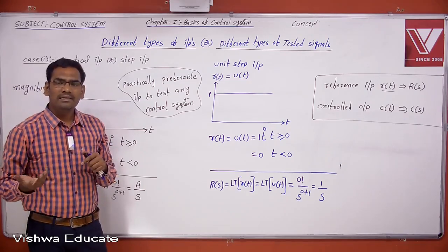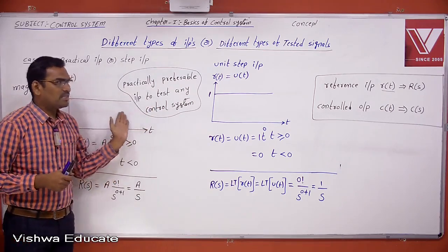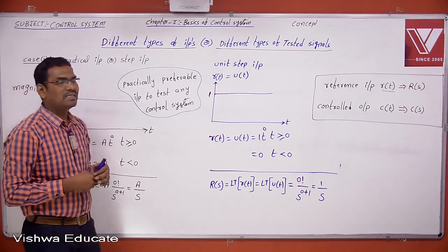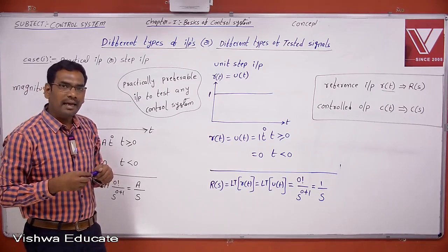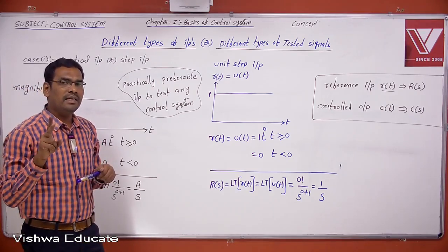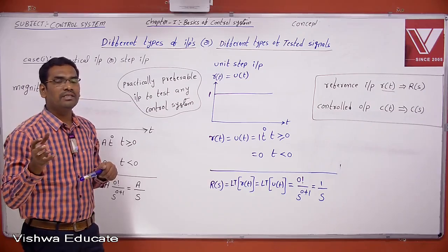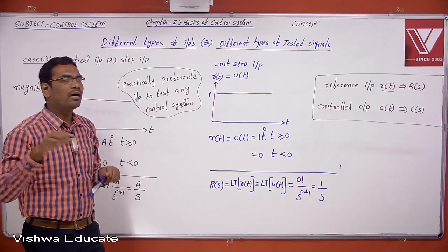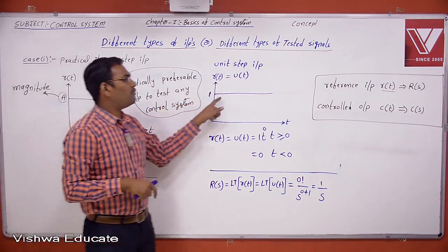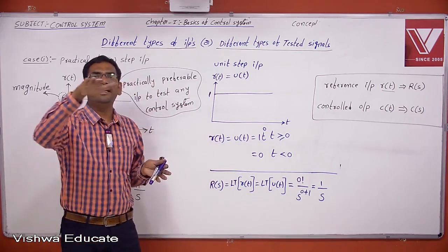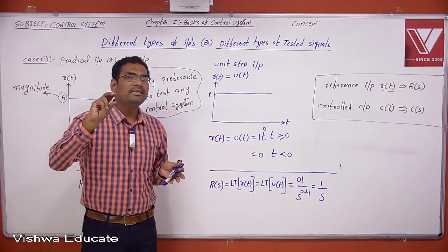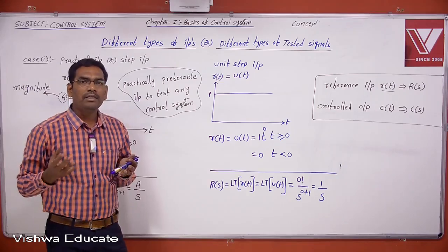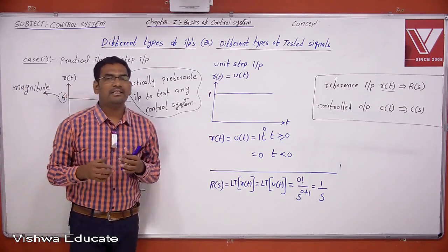In the same manner here, the system behavior is changed by changing the system parameters. What are the system parameters? The system parameters are gain and time constant. Change the system gain and the system time constant, and the behavior changes. After changing the behavior, you compare with the reference level to see whether that behavior is good or not. Therefore, the reference level should always be maintained constant so that you can easily calculate the error value. Once you know the error, you can estimate your performance.